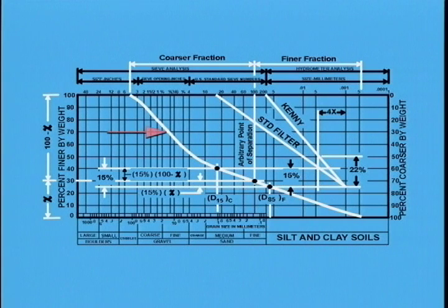Now let me summarize the key items in the design of filters. 1. Materials whose minus 200 sieve fraction is composed of non-plastic silt and rock flour require much more stringent filter criteria than materials containing plastic fines. The fines for both the Tabella and Ludington blankets were non-plastic fines. 2. A widely graded material containing gravel, sand, and non-plastic fines must meet self-filtering requirements to be stable. Gap-graded materials are especially suspect.